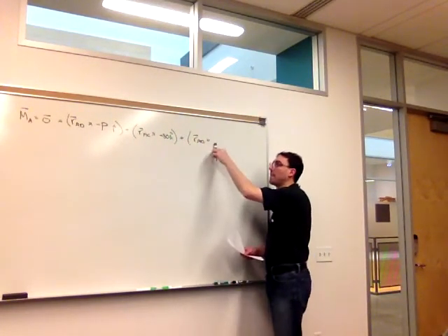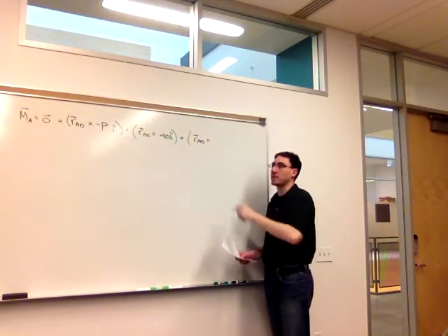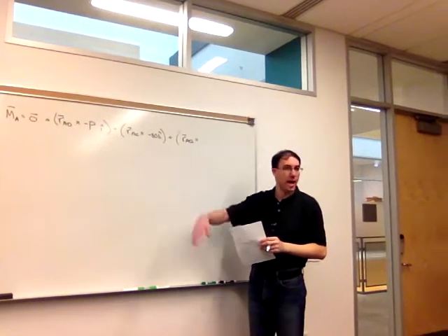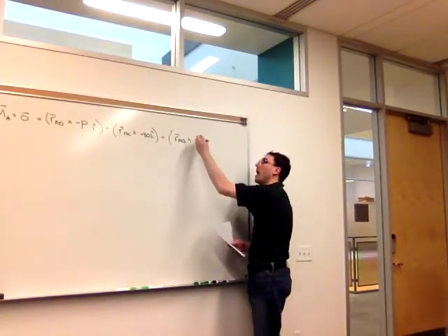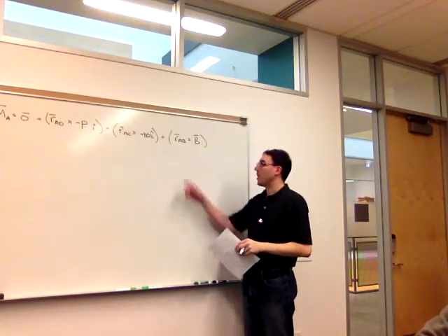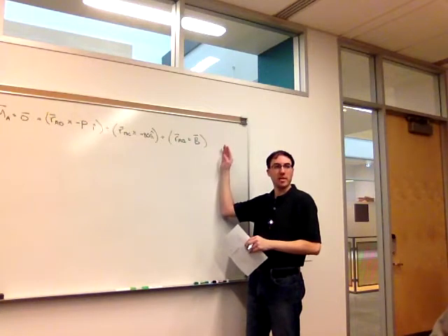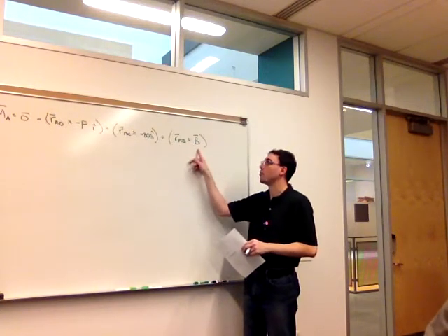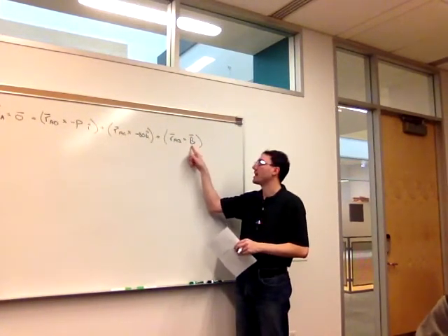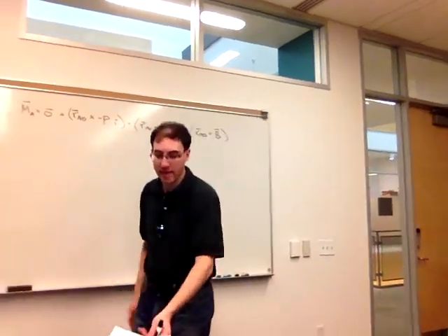Right, so at B, this is where we can save ourselves a little bit of time and effort. There's actually 3 forces that act at B, at least according to my free body diagram, BX, BY, BZ. I'm going to collectively call that vector B. Because they're all acting at the same point, instead of doing 3 separate cross products for each force at B, I can just do 1 cross product and have each of the components of that force inside of it. So it's a little bit of condensing this way.